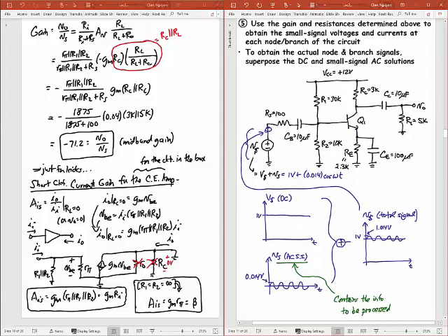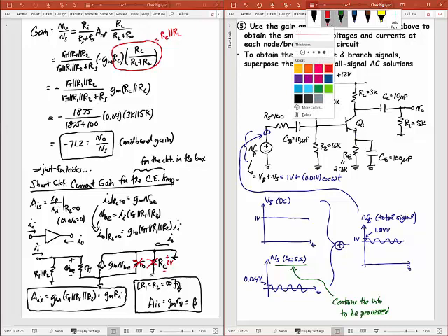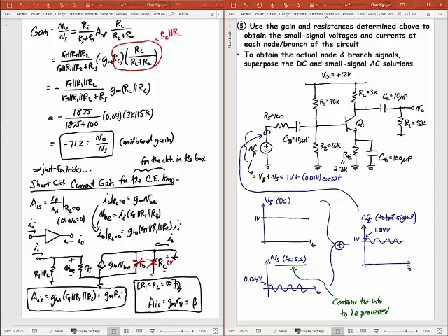Okay, so back to this, right? This was the original problem we were looking at. It was this transistor circuit here, and we knew that the input we were applying was 1 volt DC and an AC voltage with an amplitude of 0.01 volts. It's going to be at some frequency that's in the mid-band range of this, and the total signal there is just the sum of those 2 signals. Okay, what I'm interested in now, and why I did all of that work, is I want to know what the voltage is right here. What is that voltage? Okay, if I want to know that voltage, then let's go to the next page.